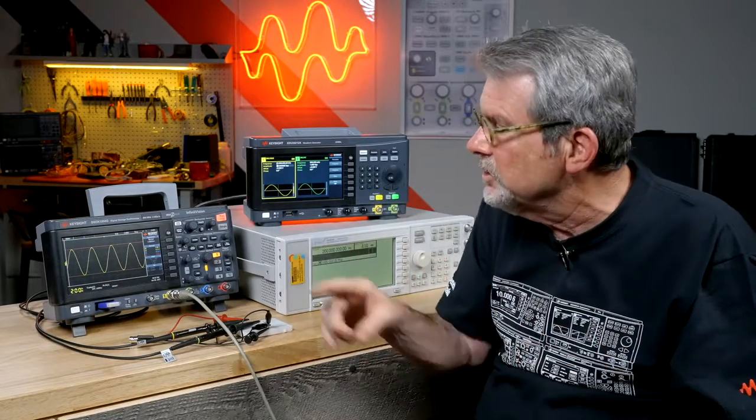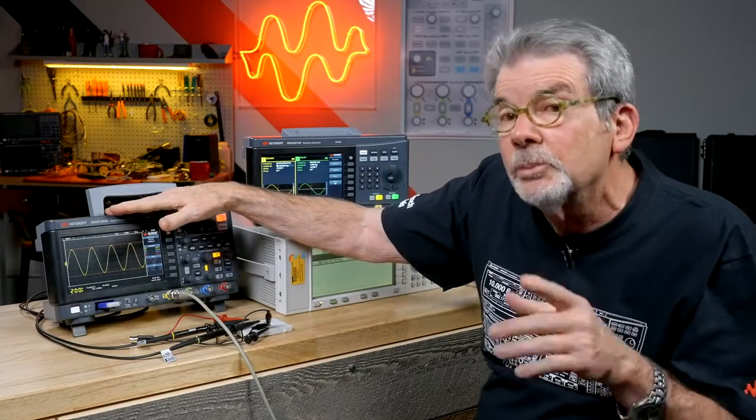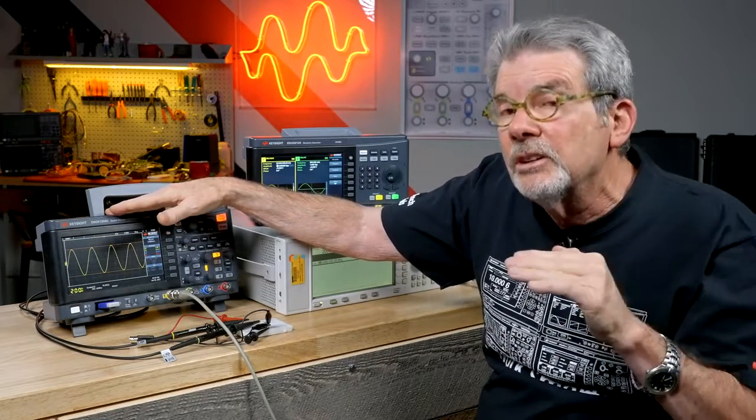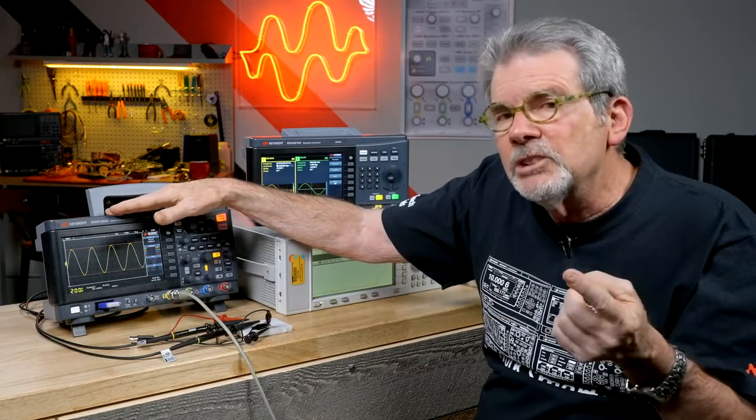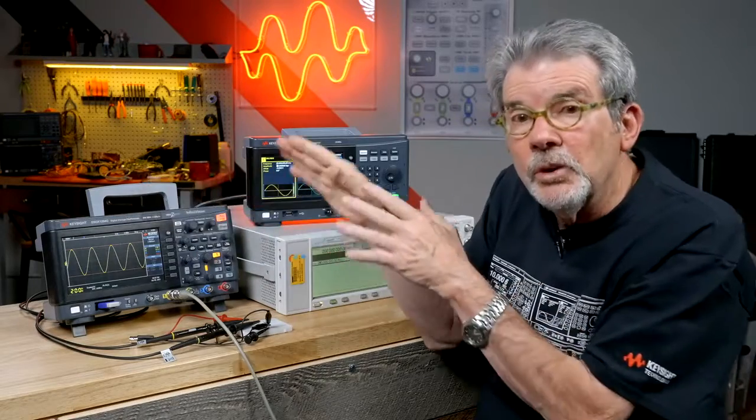My recommendation is that for lower bandwidth scopes of 1 gigahertz bandwidth and lower, the sample rate should be 4 to 5 times higher than the bandwidth. Here we have 10 times higher, so we're above that 4 to 5 times criteria. Now, higher bandwidth scopes, multi-gigahertz scopes, can come a little closer to the Nyquist, and they can do about 2.5 times the bandwidth for the sample rate. And again, that's explained in the